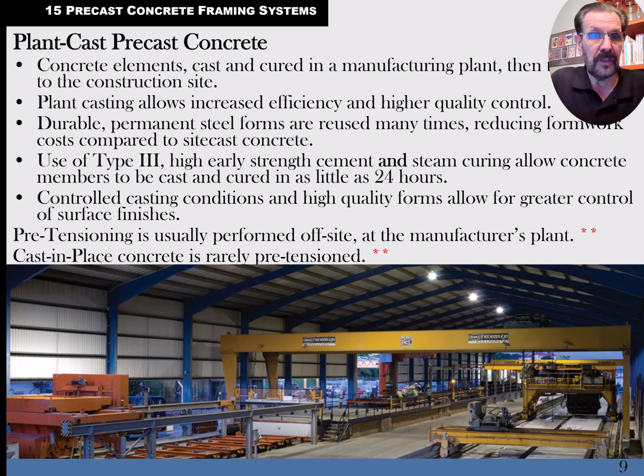So, as I mentioned, this is showing an indoor pre-stressed concrete plant where they actually make hollow core slabs. I'll have to show you an example of that first. But just a couple of things in here. We very often in precast concrete will use type 3 high early cement in the concrete mix in order to speed up the setting of the concrete, and maybe steam curing, especially in wintertime climates. You wouldn't need to do that in the summer so much, but it keeps the concrete moist. More importantly, in cold weather, you need to keep the concrete warm.